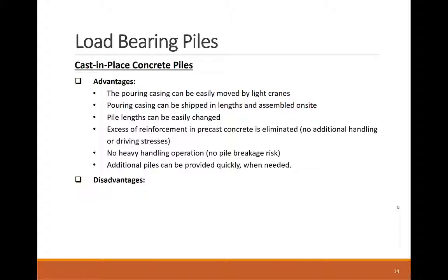There is much less quality control power for the contractor when constructing these piles, as there is no reliable way to see what's happening deep there in the pile hole. This means that necking and wasting can happen somewhere along the pile depth when the hole sides are not perfectly vertical.